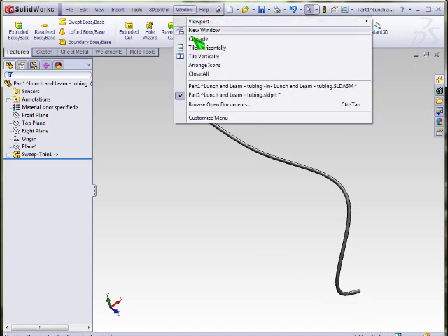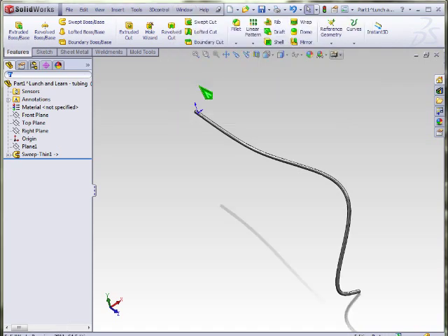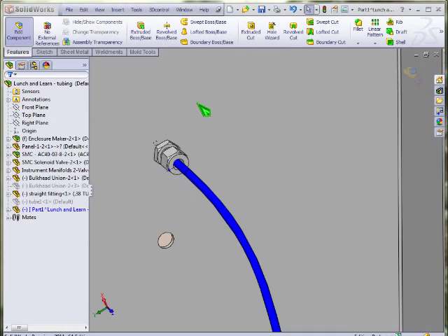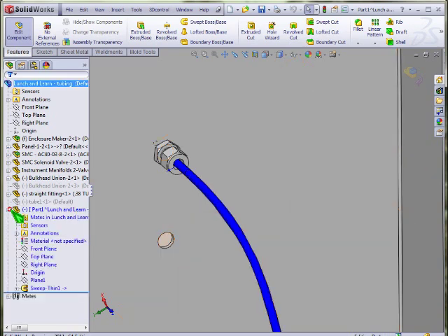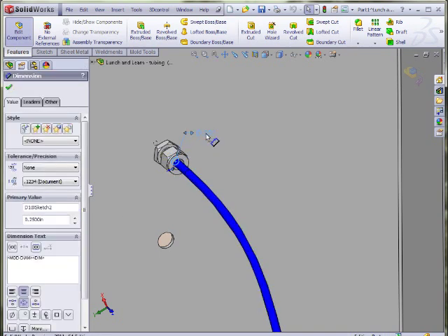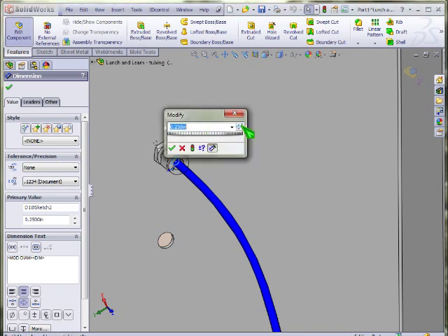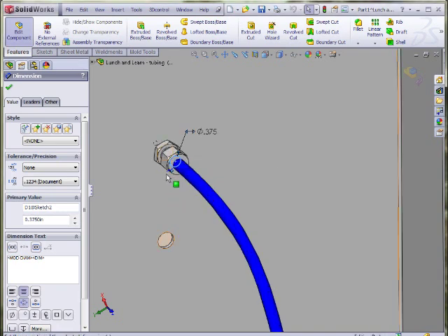And there is our final tube. We'll move back to the assembly. I made the diameter 1/4 of an inch. Should have been 3/8. Easy to fix. Double click our feature. Double click the sketch in this case, and I'll just adjust that dimension to whatever it needs to be. We'll rebuild it right from here, and you can see that becomes 3/8 now.